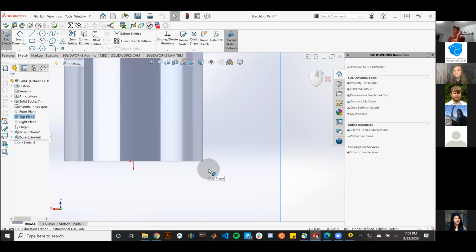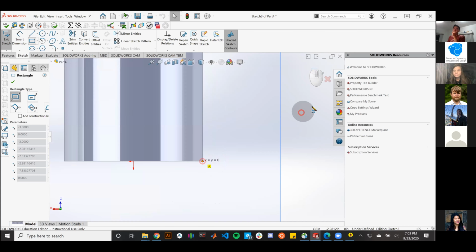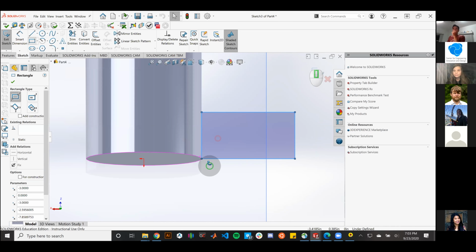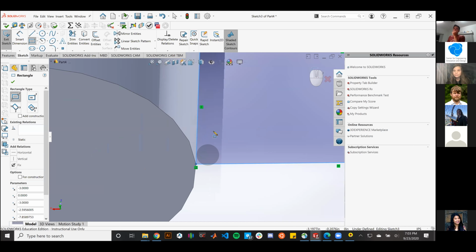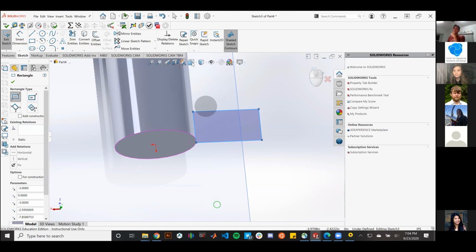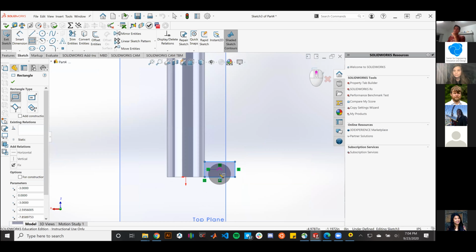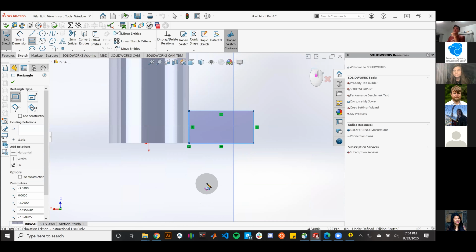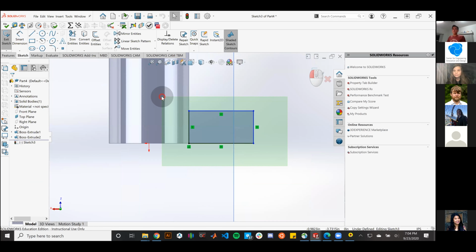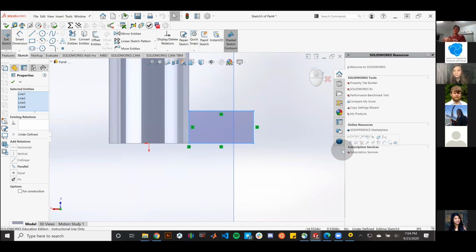What's a little tricky right here is that if we were just to make a fin like this, it wouldn't actually connect to our bottom body tube, right? Because as we extruded this out, there'd be a little gap between the fin and the body. So we're going to cheat a little bit by instead making our fin start on the inside of our body tube. So in order to delete this, I can just drag and select all of it and then press the delete button.